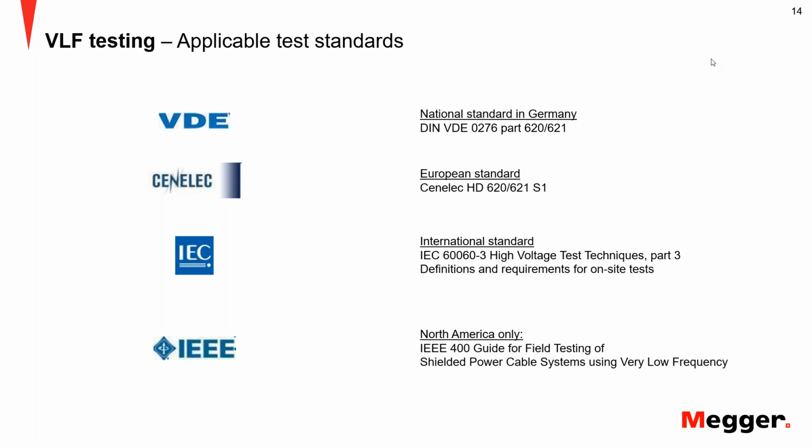And it goes through these steps: 50% of operating voltage, 100% of operating voltage, 150% of operating voltage. Based on this process, you measure the stability, the mean tan delta, and the tip up. And the tip up is what you described. So these are two different things. The one is the withstand test. The other one is the tan delta diagnostics test.